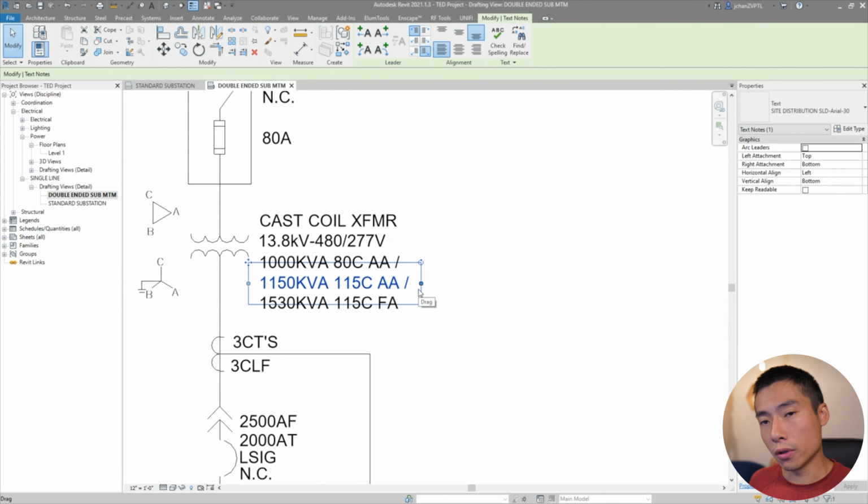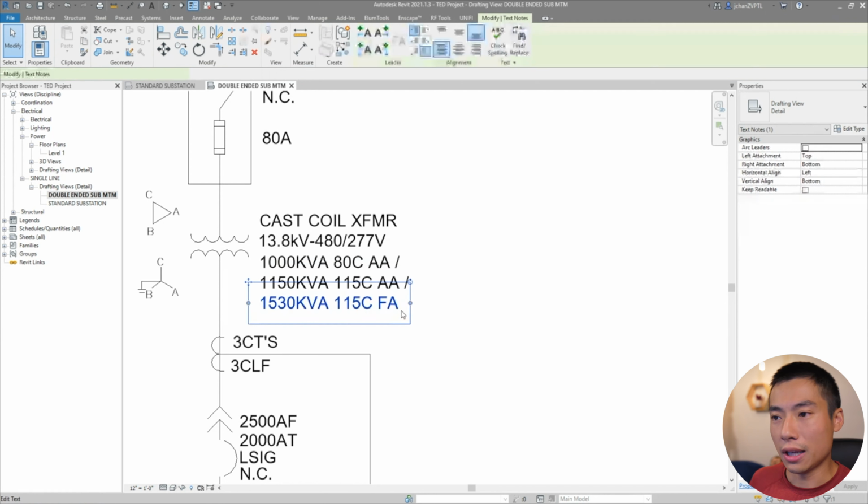And if you have future spare capacity that needs to go on, or something adds onto the system for future that needs to get picked up, well, that's when you rely on your 150C forced air setting. But the beauty of this is that you can have a facility that remains functional even if you lose a primary service or you lose a transformer. You can close the tie and the buses can shift their loads back and forth automatically without any downtime.